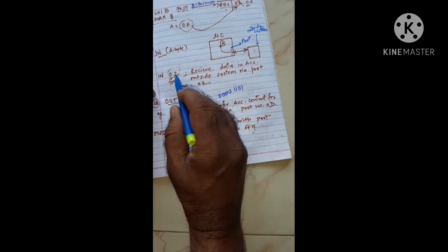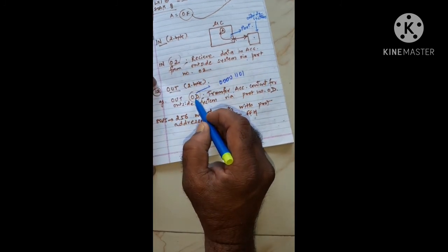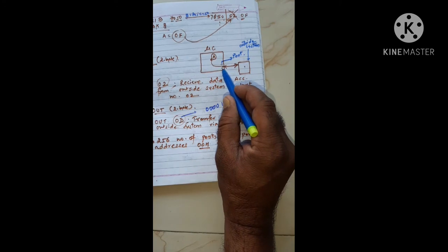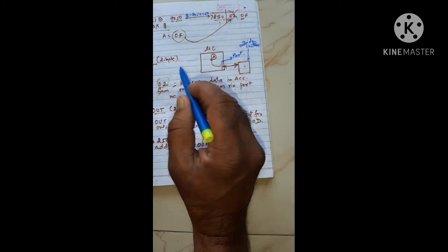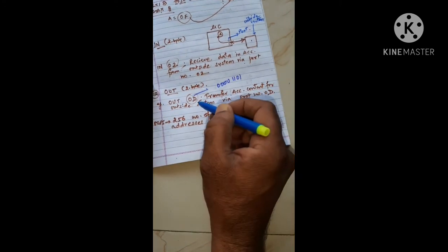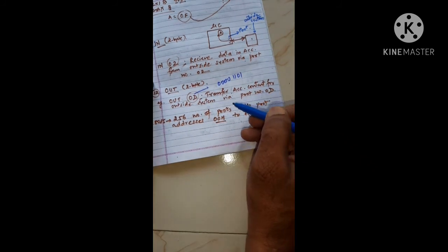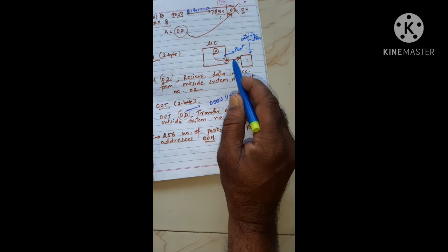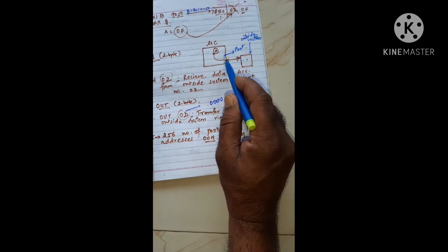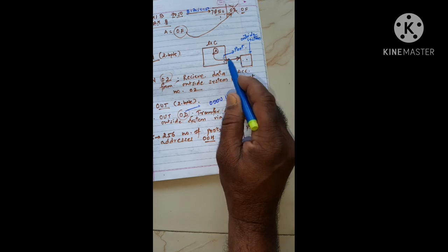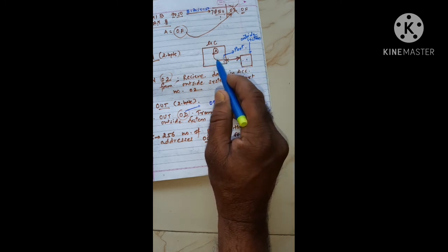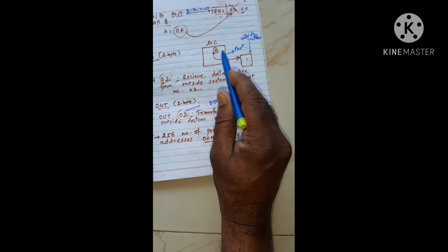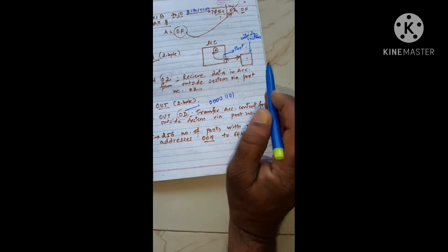Like 02, this 0D is also one of the ports on the microcomputer system, through which data can be sent out or taken in. Only the port number on which that system is connected should be used to send data out or take data in between the accumulator and the outside system directly.